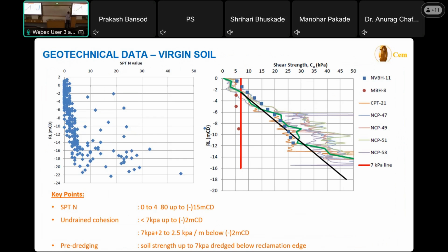Why? Because this data is also vane shear data, but these are the lab vane shear data. I put it in that list because whenever you are taking samples in this kind of very soft soil, you extract those samples from the UDS and carry out the lab vane shear test, and it is further remolded. So the strength is much lower than what is actually in the field. So for this kind of soil, we should not carry out lab vane shear tests, which under-predict the values.